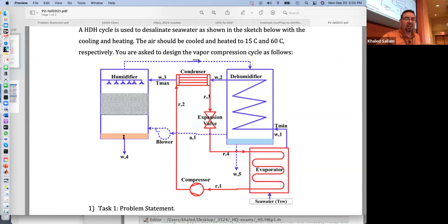Okay, so you just send the air through, and what happens here? You throw it through a bunch of sprays. We will discuss them in a minute when we go through humidification. But basically, you can tell that if this water comes here, and there is a lot of this packing material, it's similar to a cooling tower. They want the air and the water to hang around for a really long time.